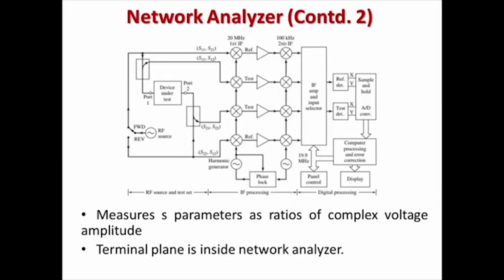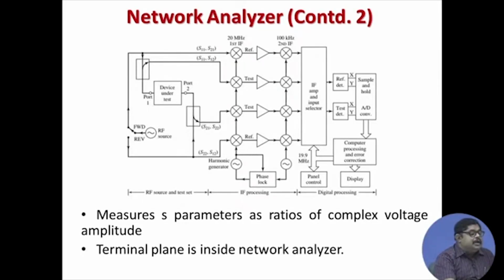Unfortunately, the terminal planes of voltages etcetera are inside the network analyzer, because when you are extending a port, the network analyzer is definitely sitting inside. So, its port definition is different. What we are seeing as a port is not always its port. That is why it commits some error, which gets corrected in the error correction.